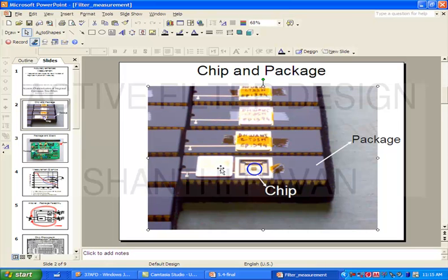And these are all the pins of the package, correct? The pads on the chip have to be connected to pins on the package. So what is done is that this thing is stuck using glue. For all practical purposes, some kind of glue, some epoxy kind of stuff, right? We make sure that when the package moves, the chip doesn't move. So for mechanical stability, you can't just leave the chip floating with wires hanging all over the place. The silicon die is actually pasted in the package cavity, right?